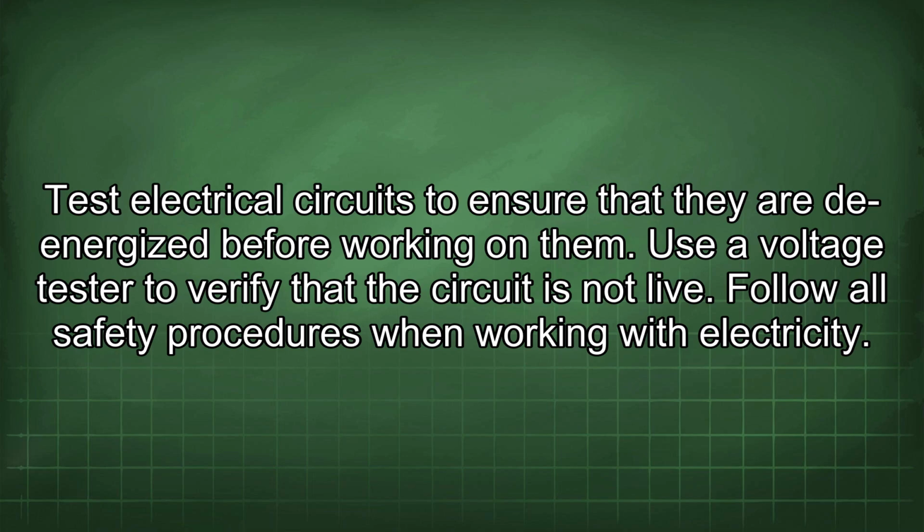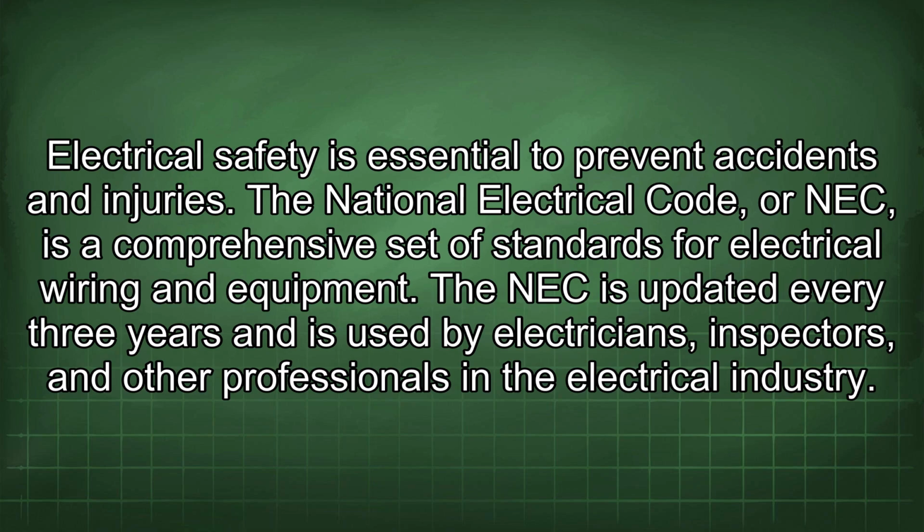Test electrical circuits to ensure that they are de-energized before working on them. Use a voltage tester to verify that the circuit is not live. Follow all safety procedures when working with electricity. Electrical safety is essential to prevent accidents and injuries.